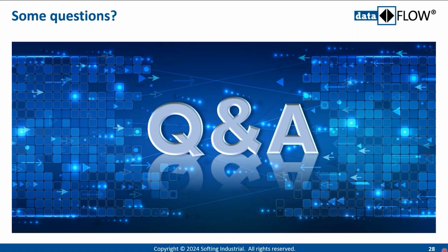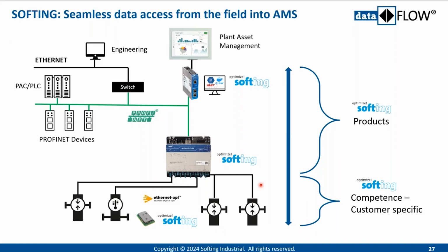Fabrizio Corti, could you tell again the distance which can be covered? Trunk and spur. Okay, it's two things. For the existing technology, if you look at the north side, okay, do you see the picture? Yeah, okay. So to the north side, this is normal Ethernet connectivity. So you have the 100 meters if you use copper, or you have 2 to 3 kilometers. A lot of people are using fiber for that. To the south, what's in the spec are 200 meters to each of these devices, and it's depending on the cable.